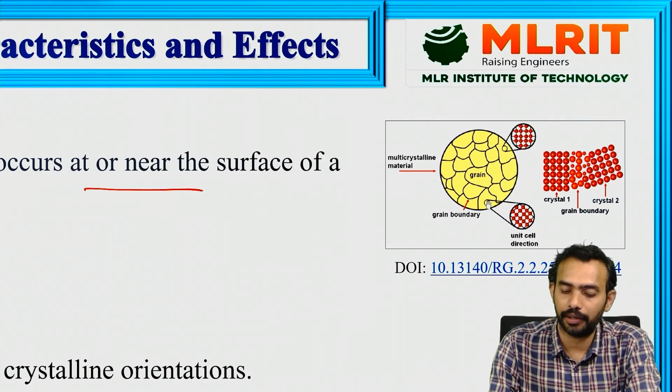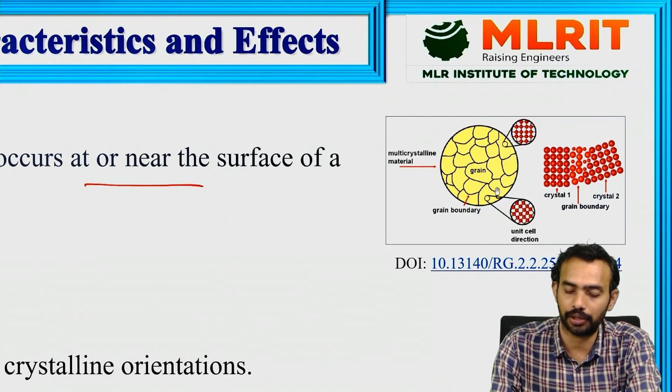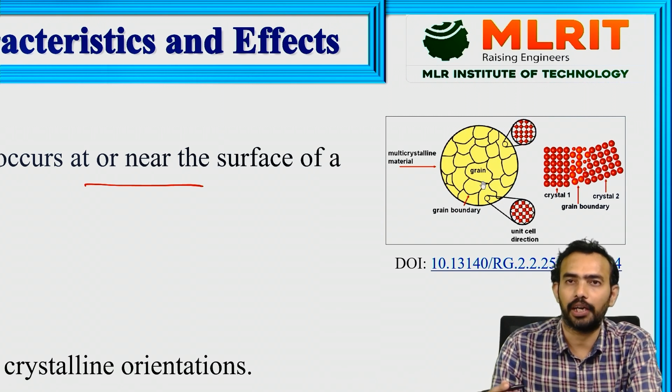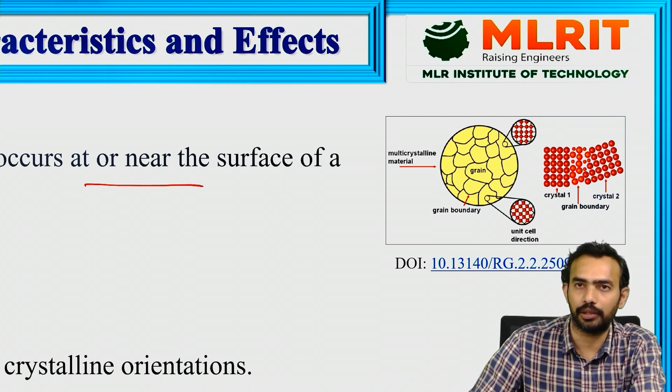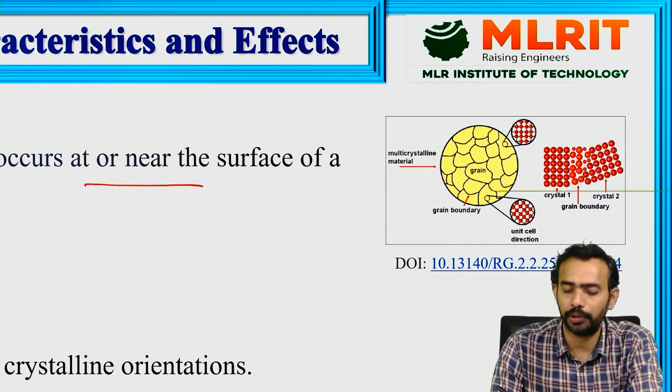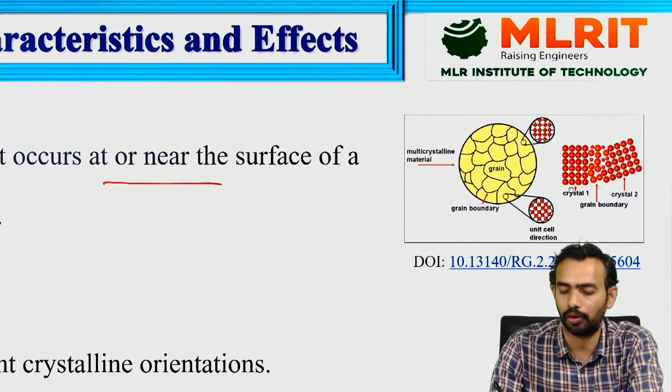This is one grain and this is another grain, individual grains. The common region that you see is treated as the boundary for both grains. In those regions also atoms will be staying. Those atoms are considered to be the grain boundaries, and that is considered a defect region, because there is no regular arrangement observed. The atomic arrangement will not be regular. It will not be the regular arrangement of grain A.